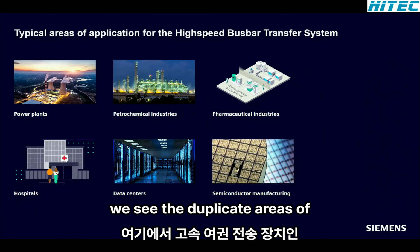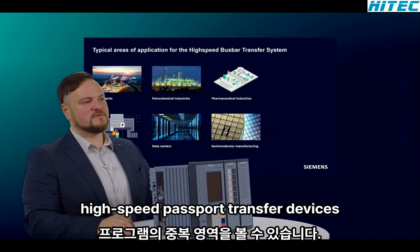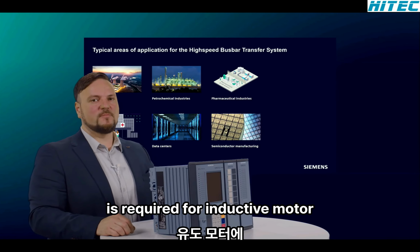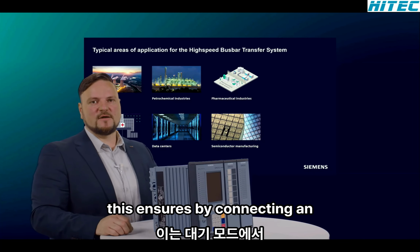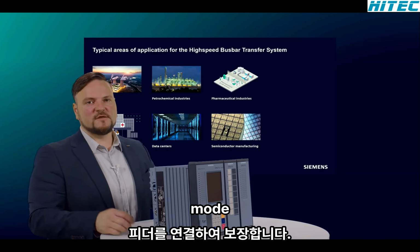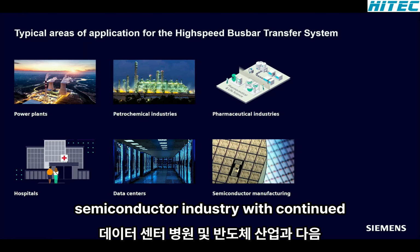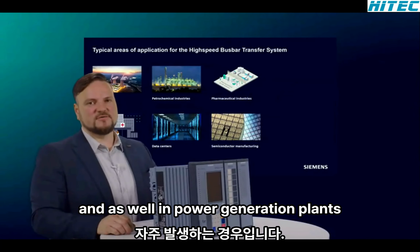Here we see the typical areas of application for HSBT functionality. A high-speed busbar transfer device is typically required where a continuous power supply is needed for inductive motors operating critical parts of a production process. This is ensured by connecting an alternative incoming feeder in a standby mode. This is often the case in the petrochemical, pharmaceutical, data center, hospital, and semiconductor industries with continuous processes, and as well in power generation plants.